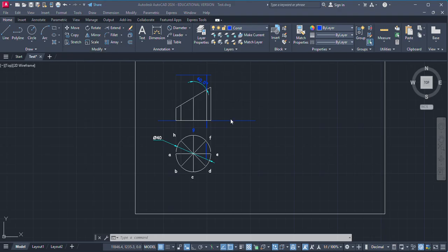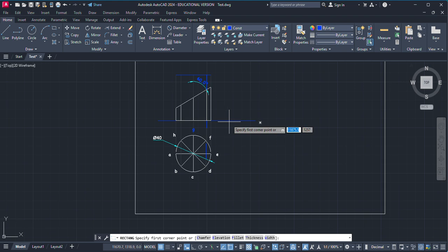So we'll draw a small rectangle, and we need 8 rectangles of this length. We will make the first rectangle here, whose height is 50 mm and length is 15.7. Then we will make 8 copies of this rectangle. First point is here.